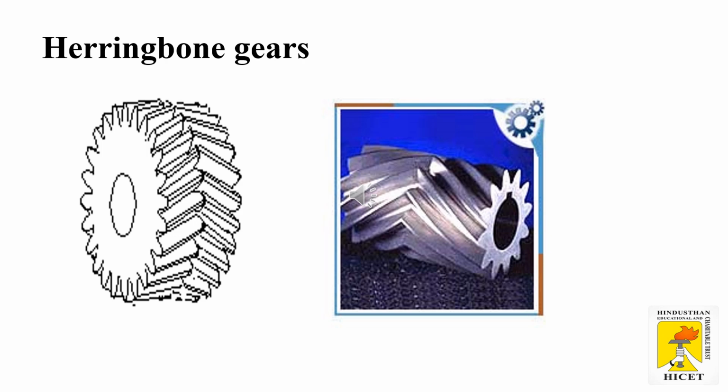Though herringbone gears have high load carrying capacity, they are costlier than single helical gears. Herringbone gears are limited to high load carrying capacity applications such as cement mills and crushers.